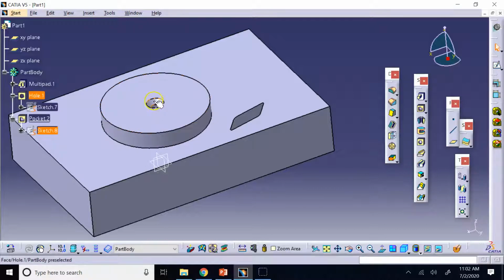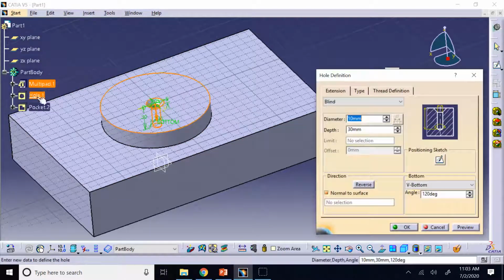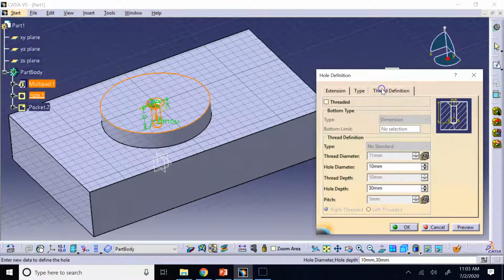Second, this command can create for you these countersunk and counterbore holes that the cut extrude does not do, unless you do two separate cut extrudes. And more important than that is, let me show you, you can create threads. Okay, so not only can you drill it, you can provide threads.